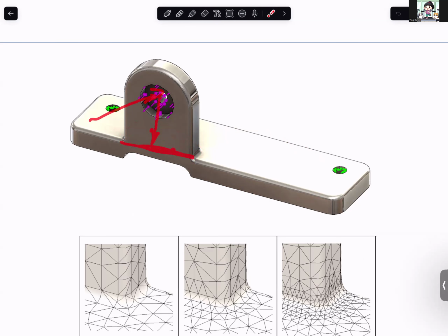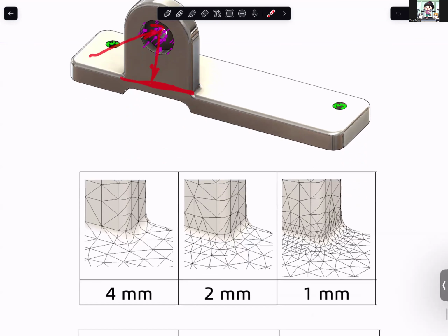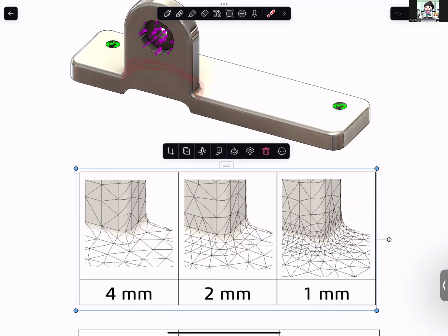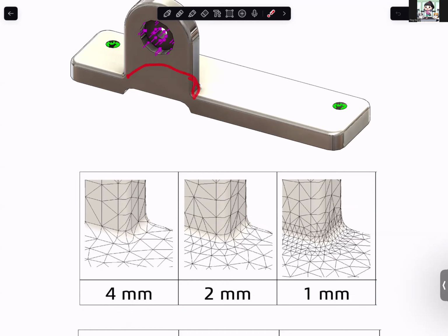The second thing is that in the real life situation, when you see something like this, it causes stress concentration, right? So we know that, that's why we need to learn mechanics of materials before we start FEA. We know that probably around this area is somewhere we need to be more careful for finding the maximum stress.